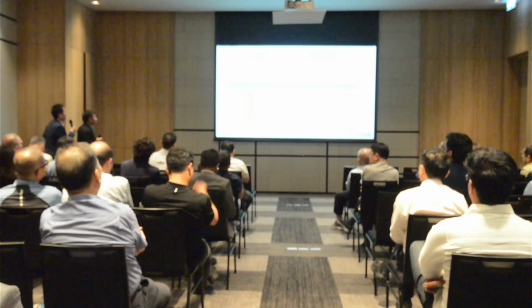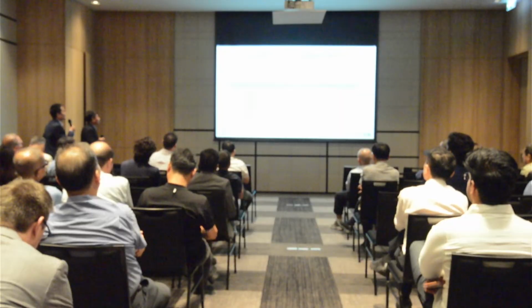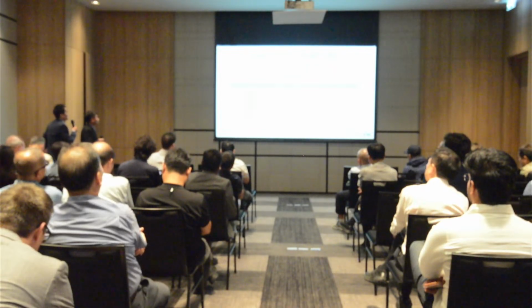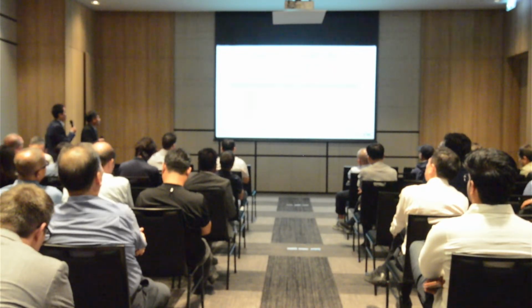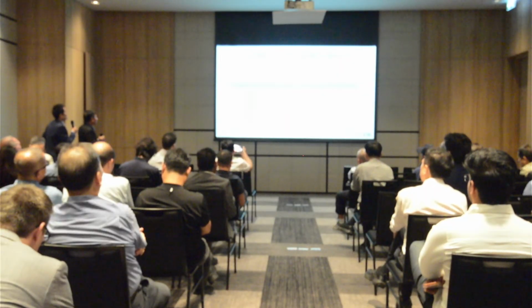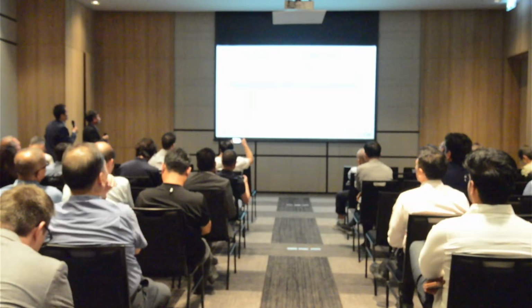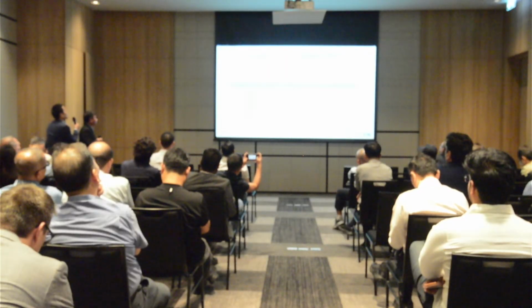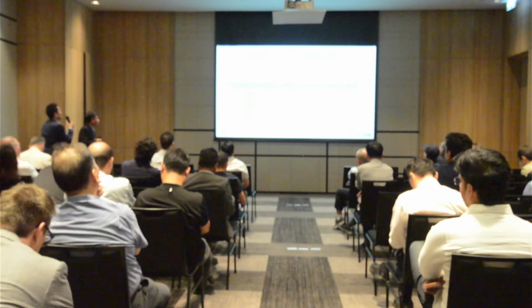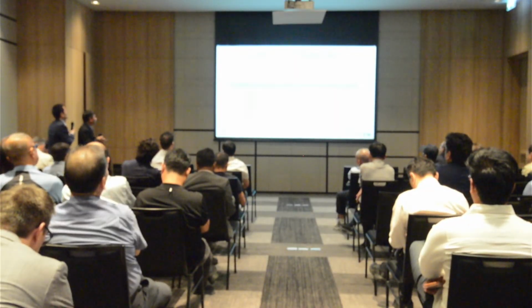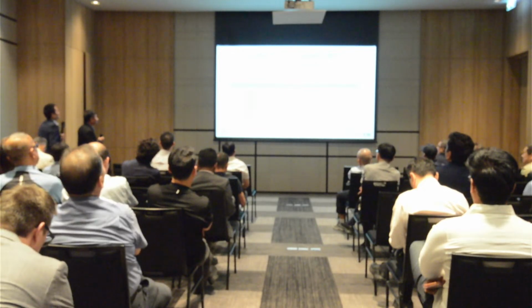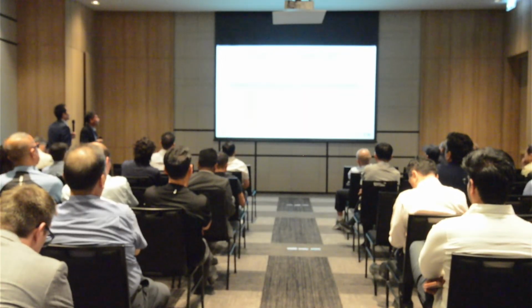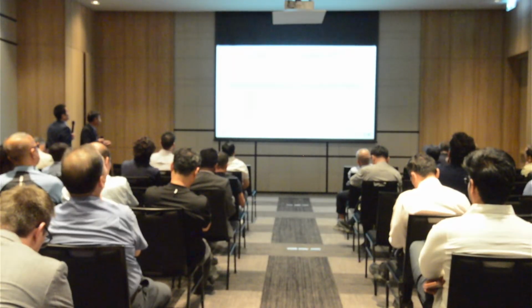The gate temperature is about 620 Celsius for semi-solid. The surface temperature of the mold is about 350 Celsius. The solidification analysis starts at about 593 Celsius. We use the average thickness of about 4.75 millimeters and follow this equation to get the filling time.